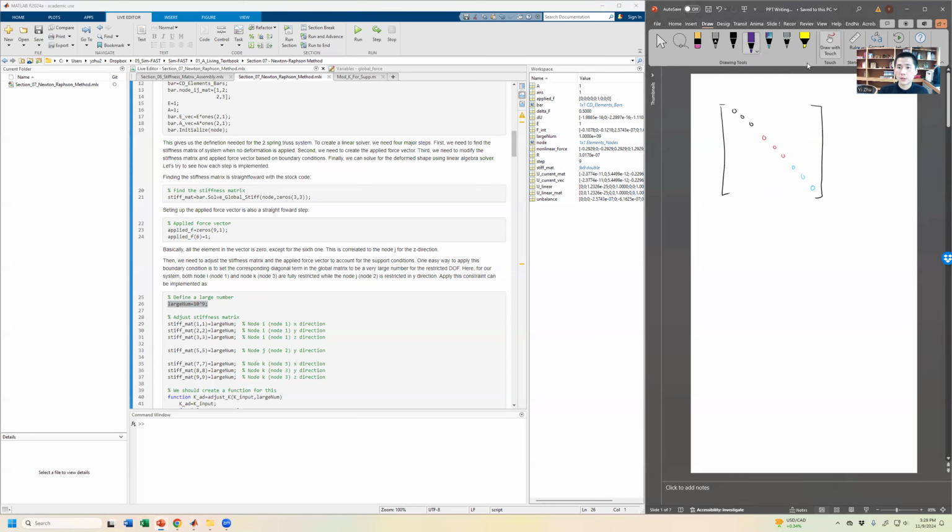And what I will do is fill those indices where I want to restrict the motion. For instance, I don't want node I to move at all, and therefore I will fill a very big number in these diagonals. Basically, because the diagonal stiffness is so large, it's going to be hard to move it. Even if you apply forces to the structure, this node will most likely not move much because of that extremely large stiffness in the diagonal. That's how the system will work. And the same thing for node K: I will get a very large stiffness there. So this is node I, node J, and then the bottom will be node K. And this is my stiffness matrix.